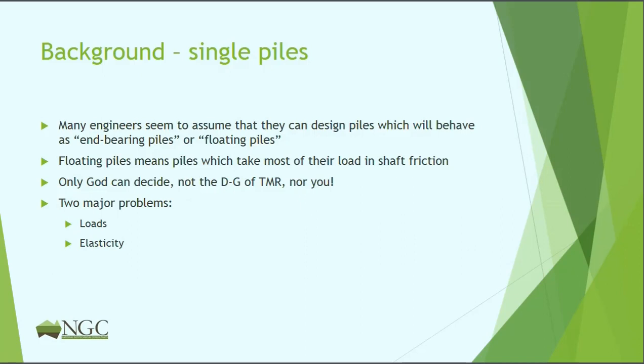Many engineers seem to think that they can design piles which are either end-bearing piles or floating piles, where floating piles means a pile which takes most of its load in shaft friction. Unfortunately, only God can decide whether a pile will be a floating pile or an end-bearing pile. With all due respect, the Director General of Main Roads can't, and neither can you, because it depends upon the loads and on the elasticity.